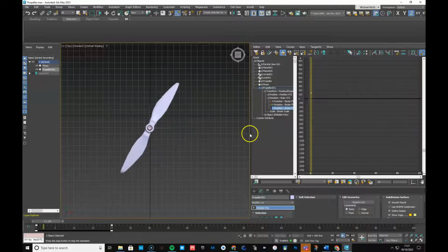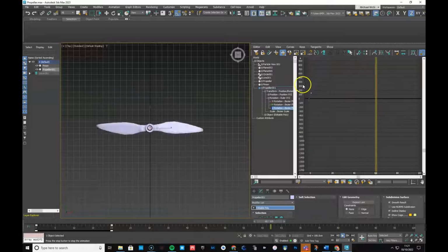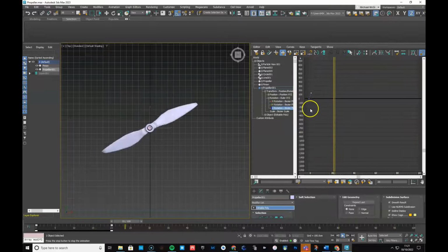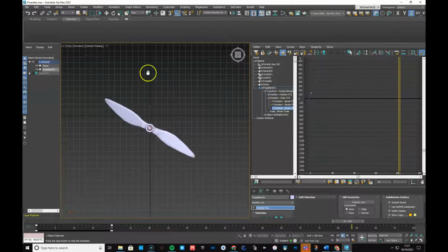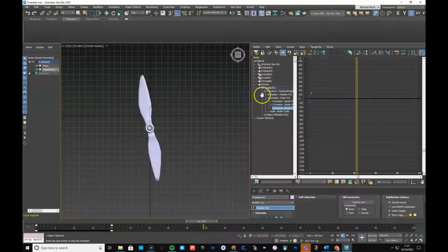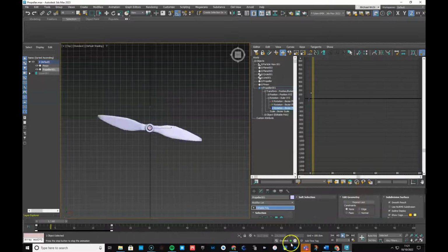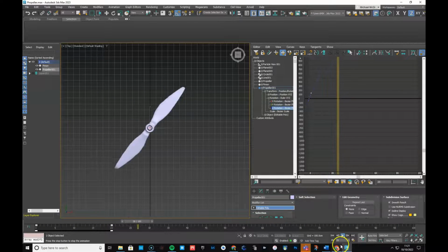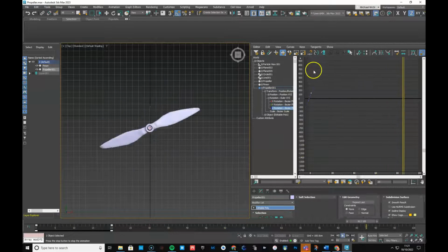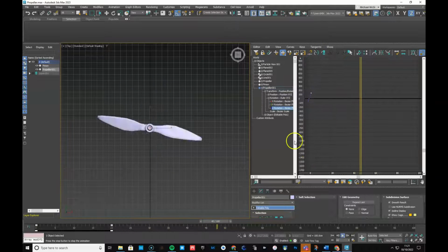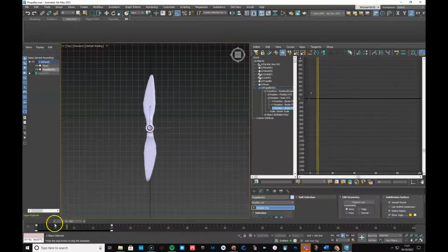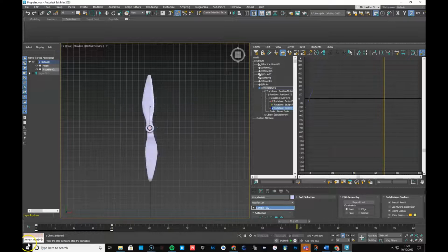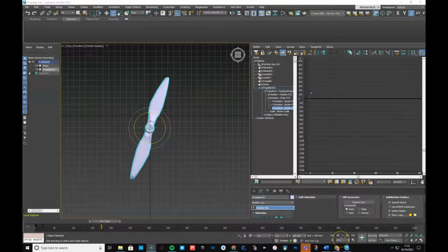So we've only had to make 2 keyframes, and we've got the animation running continuously. No matter if you change this animation to 1,000 frames long, the parameter curve out of range type will keep the linear animation running over and over. Let's test that.